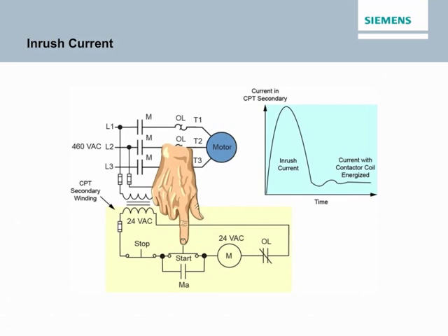As a result, if the power source is not designed to handle this inrush, the control voltage can drop below the level needed to energize the control circuit. A CPT is designed so that, if properly sized for the application, it will provide excellent voltage regulation in its secondary circuit, ensuring that the control circuit it powers receives adequate voltage.